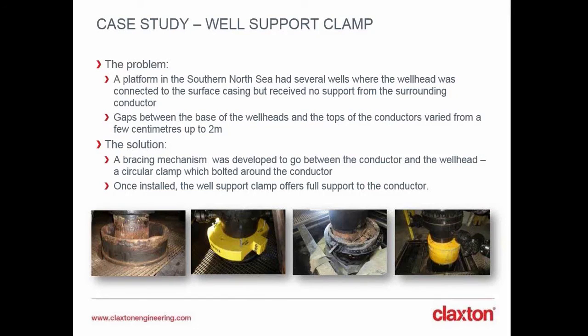They're quite different in terms of the height from the base of the wellhead to the top of the conductor. And if you look in a little more detail, you'll also see that the eccentricity is quite different as well. In order to design a suitable well support clamp, a detailed and precise survey had to take place in advance, to make sure all the correct measurements were taken and to avoid any issues during the installation. So you wanted to design a clamp, go install it, and make sure it would fit properly at location.